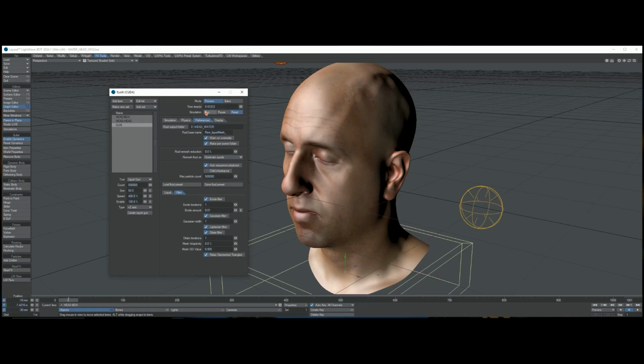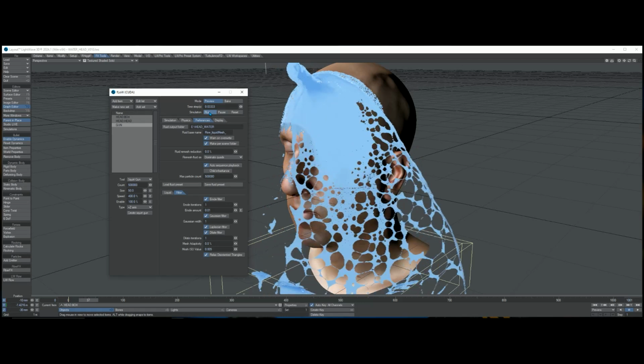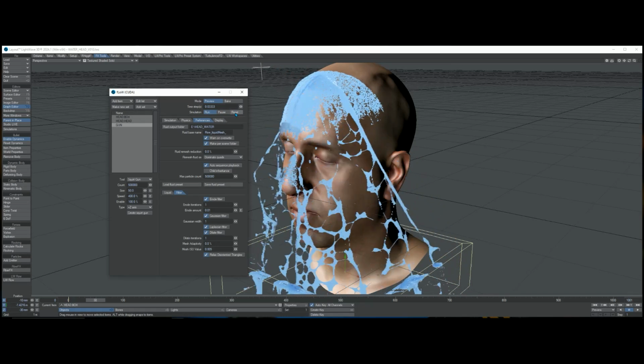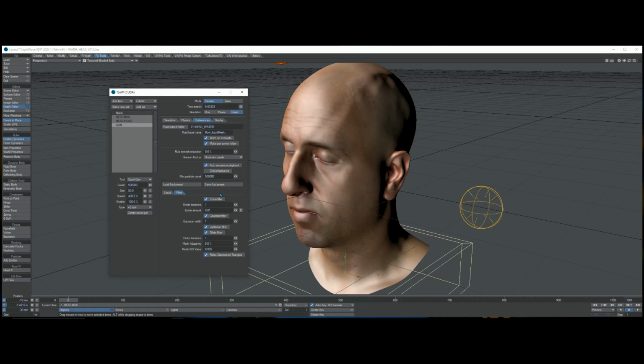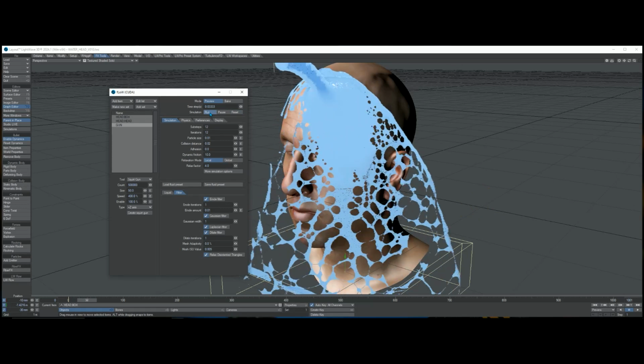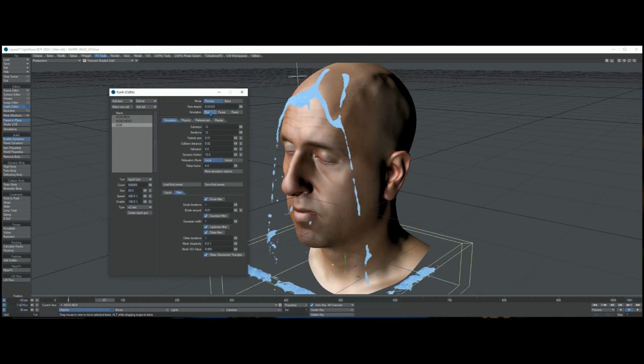So with that scene you can test and imagine in what way Flow with CUDA works, and what you can do there. In that case, that fluid can stick on the kinematic object. If you do not want it to stick, then set the adhesion to 0, and then you have the effect that it does not stick on the body. Then most of it will go.